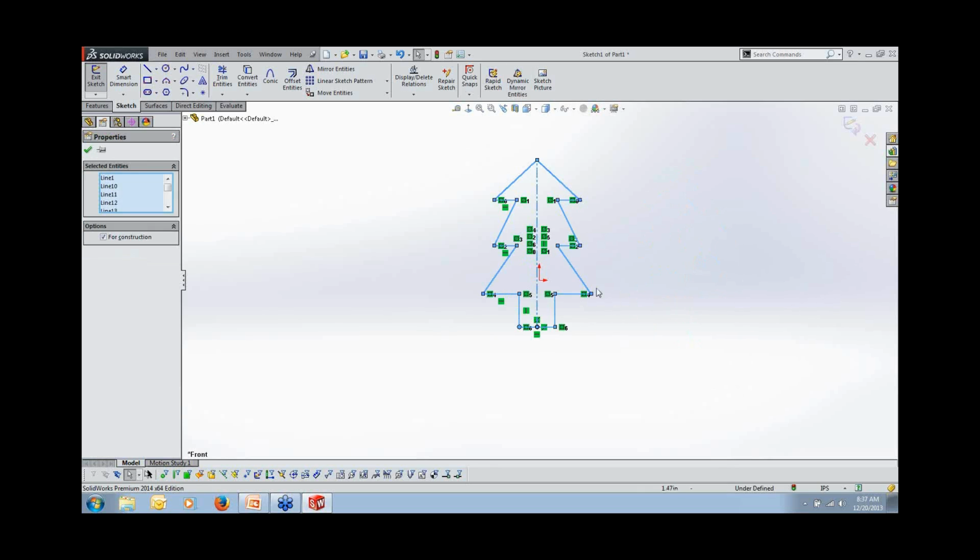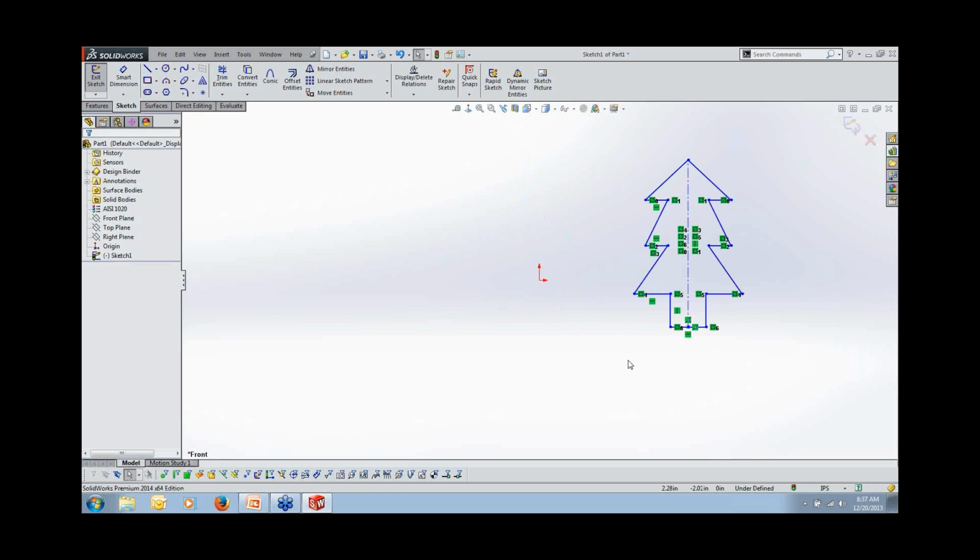But one of the things that you can actually do with that is, if you control and drag this, but release control before I drop this, so I've got my finger off the control key now, I still have a preview, and when I let go of this, it actually moves my whole sketch. So rather than duplicate it, it slides it over. And I think that's kind of a cool one. I think actually Lars told me that one too. It's kind of a neat one. I've used it a ton of times since. It's just kind of a handy shortcut.